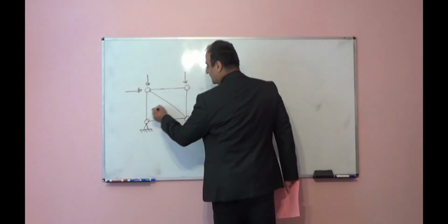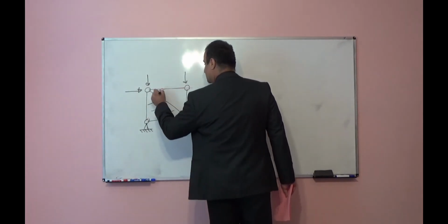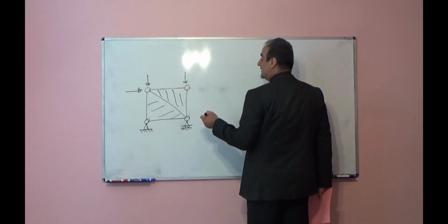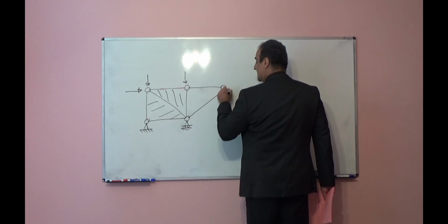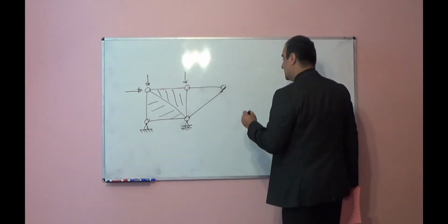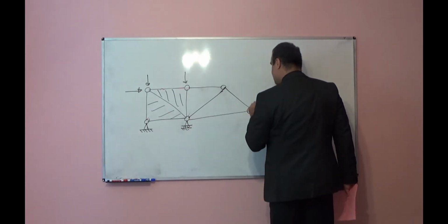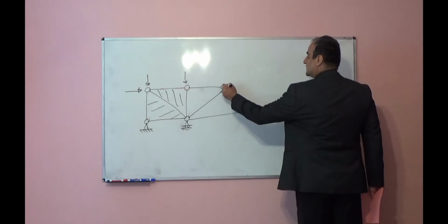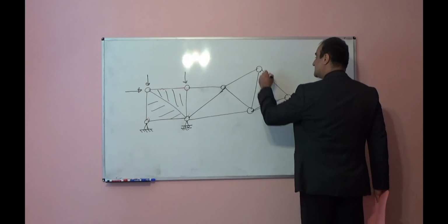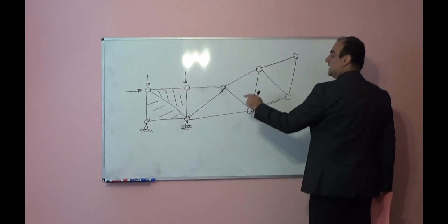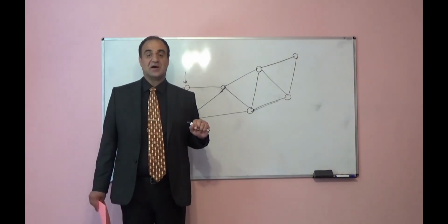you see you have one triangle, two triangles, the first triangle is here, the second one here. And if you want to expand this truss you can add another straight member and attach together using another pin. And if you want to expand more, again 2 more members, another pin, and so on. So you can develop this structure, you can make it bigger, and it will always be a stable structure. This kind of structure we call a simple truss.